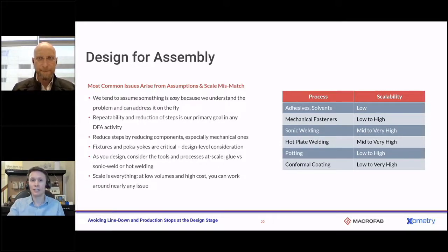Could you integrate an overhang, some location pins, and maybe just use 1 screw instead of 4 to make everything hold in place? Or even better, integrate a snap tab at a slightly higher tool cost. I could put in mounting features without actually adding hardware. So there are design techniques where all of a sudden you could consolidate and even eliminate hardware, or at least reduce part counts of your hardware, not everything, with a little bit more design forward thinking.